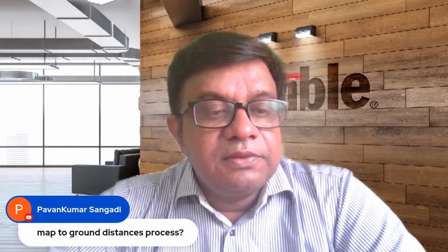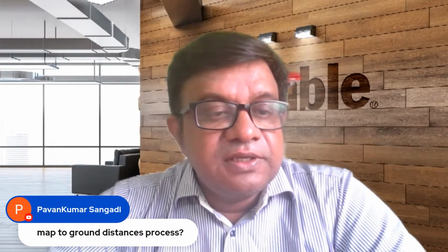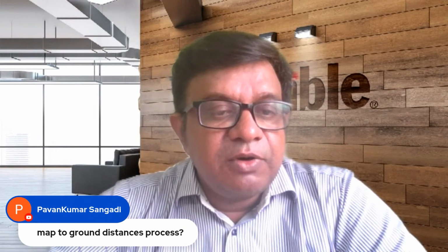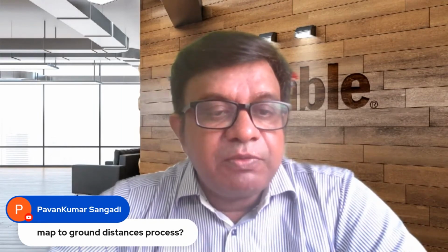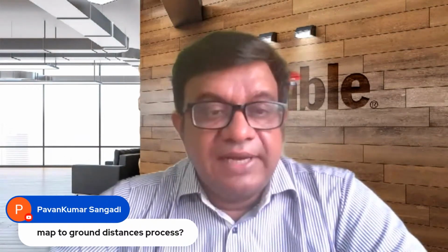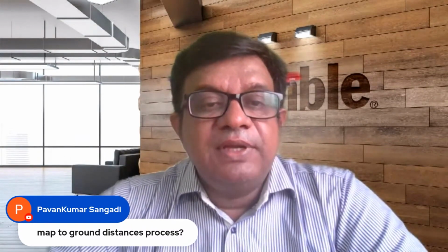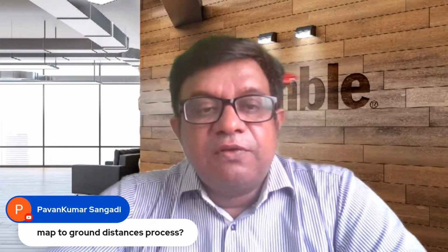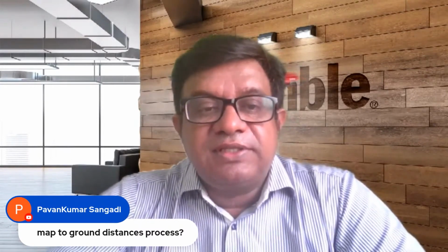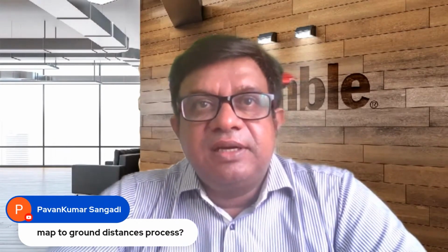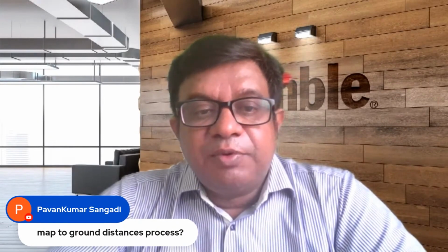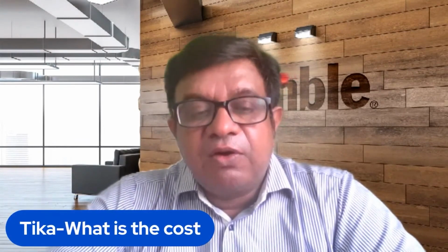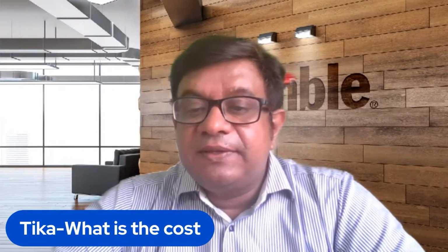Somebody is asking about the map to ground distance process. In TBC we have something called site calibration. We generally import a few sets of local coordinates and GNSS coordinates, and we do a site calibration, which generates a parameter transformation and gives you a proper scale factor for ground to grid conversion. When we export it, we have different versions for ground to grid conversions as well.